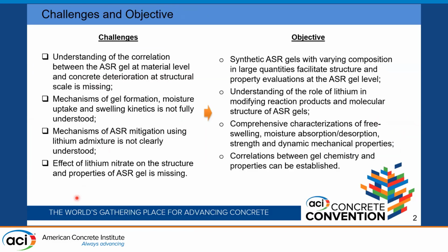Regarding the ASR gel, challenges still remain in this area. For example, the understanding of the correlation between the ASR gel at material level and the concrete deterioration at the structural level is still missing. The mechanism of gel formation, moisture uptake, and swelling kinetics is not fully understood. The mechanism of ASR mitigation using lithium admixture is not really understood.